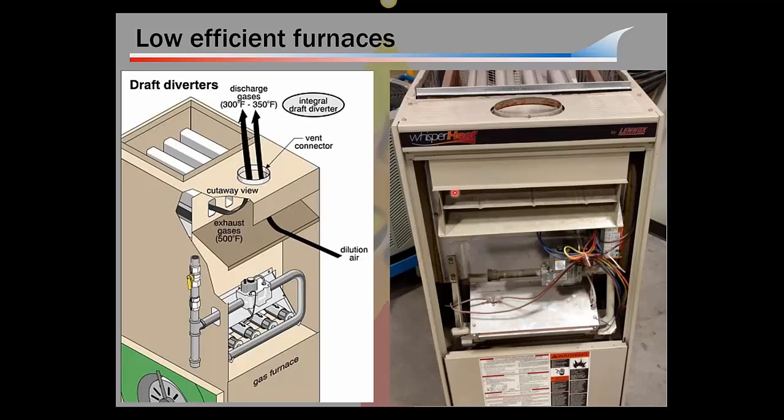So anyway, this is just another thing I found that, you know, guys just didn't know. They're up here in the flue, but when you have this big draft hood or draft diverter and you're going to test these furnaces, get into each exhaust port. And you can stick your probe right up through there and get it right into each exhaust port.